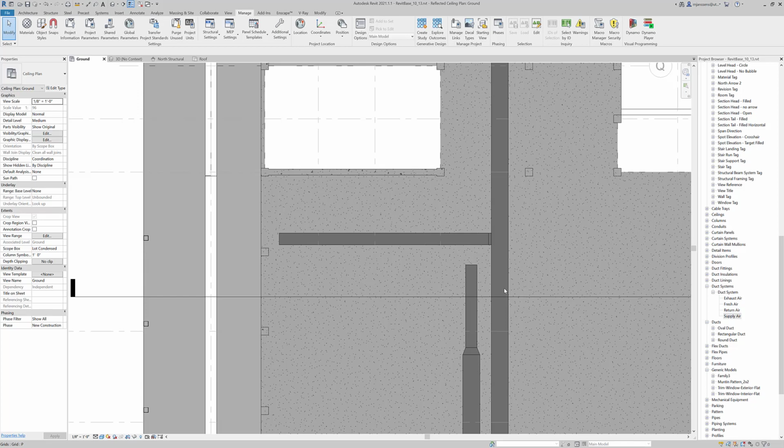One of the last things I'm going to talk about now are air terminals. Air terminals are basically the last part of the mechanical system where the air comes out. Now for this class we're using 24 by 24 diffusers for the face, and then they have a 12 by 12 connector. So I've uploaded these for you on Canvas.